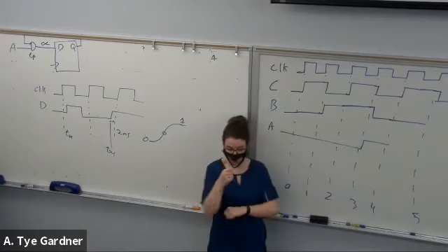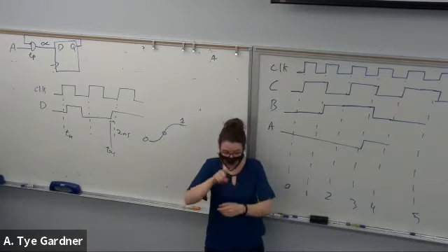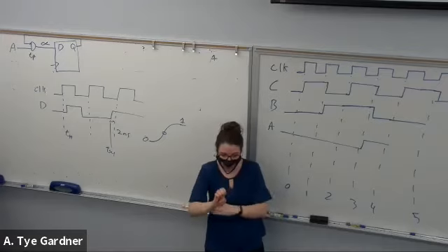Hold time is the amount of time your inputs need to be stable after the rising edge of the clock.